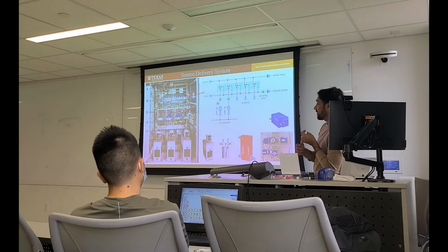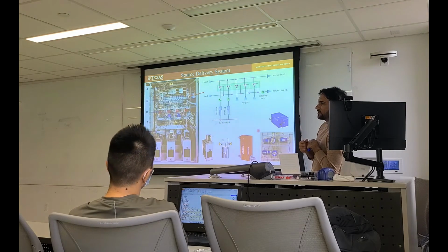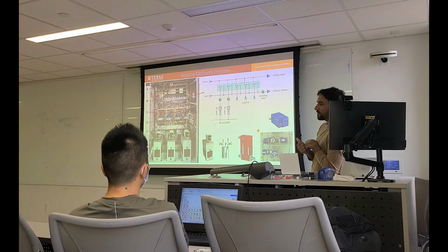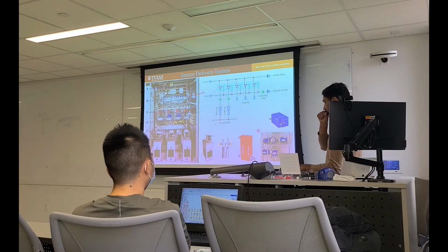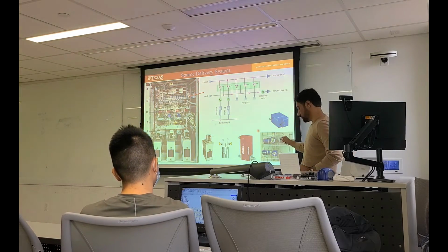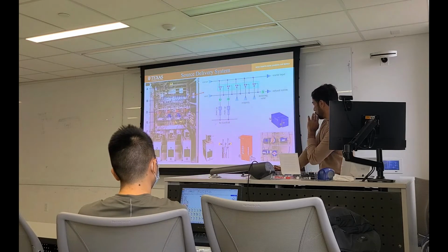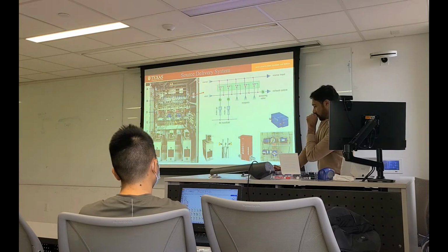Nowadays they are using nitrogen also. So normally open pneumatic valves means they are always open if you have not supplied the compressed air. When you supply the compressed air, they will be closed. So you can actually control them through your recipe.